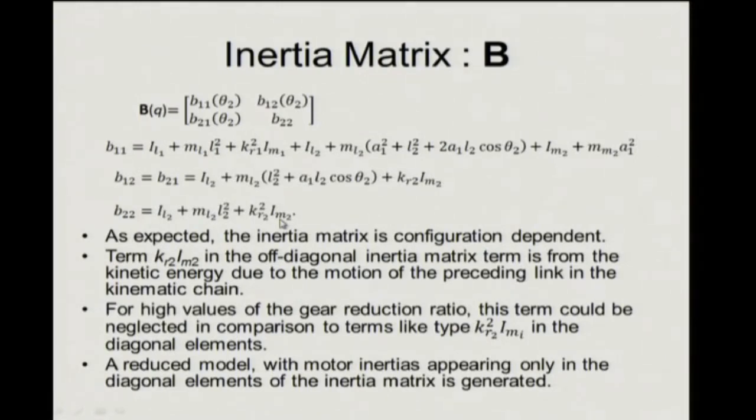So, under some load they will easily run at 1000 rpm, and you do not want the robot to move around at 1000 rpm. How many hertz is that? 1000 divided by 60, it's 100 by 6, 18. So, you do not want it to go around 18 times in a second. In fact, you do not even want it to go around once in a second, that is too fast. So, it is not unusual to see a reduction ratio of 50 or 100 from the motor, not necessarily by the belt that we have shown schematically in our analysis, but it could be through gearing. It can be made very compact, especially if you are using epicyclic gearing.